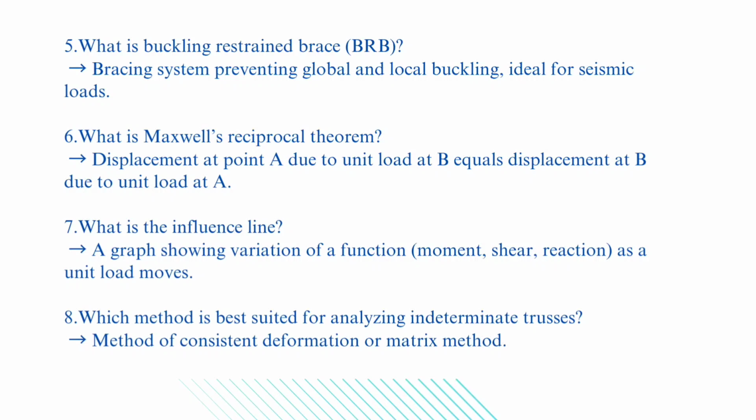Now the next question is, what is the influence line? An influence line is nothing but a graph showing the variation of a function like moment, shear, reaction, etc. as a unit load moves. Now question number 8, which method is best suited for analyzing indeterminate trusses? And the answer is, the method of consistent deformation or the matrix method is best suited for analyzing indeterminate trusses.